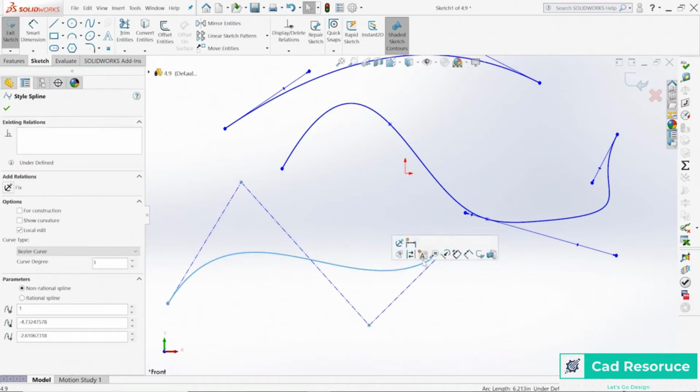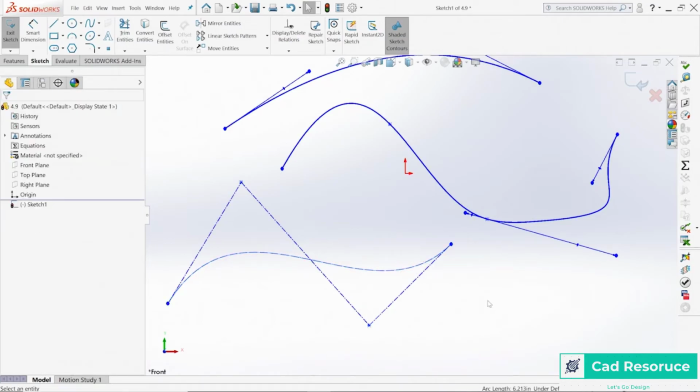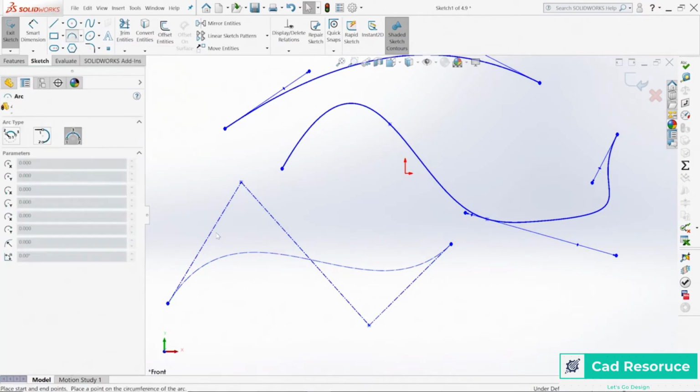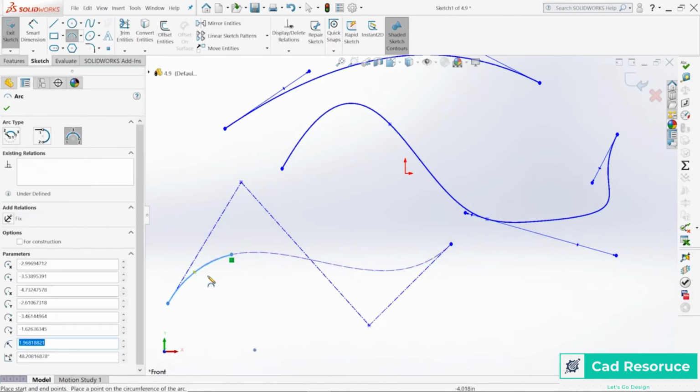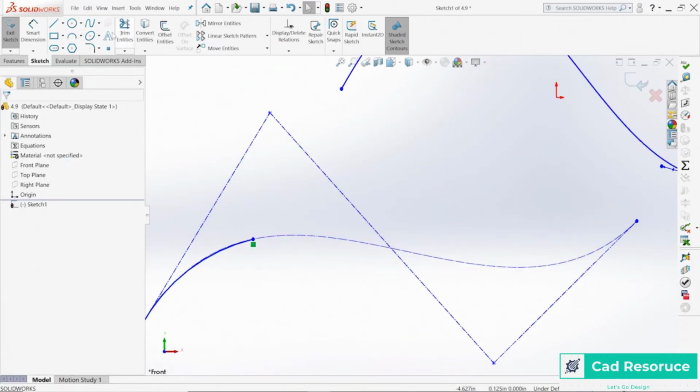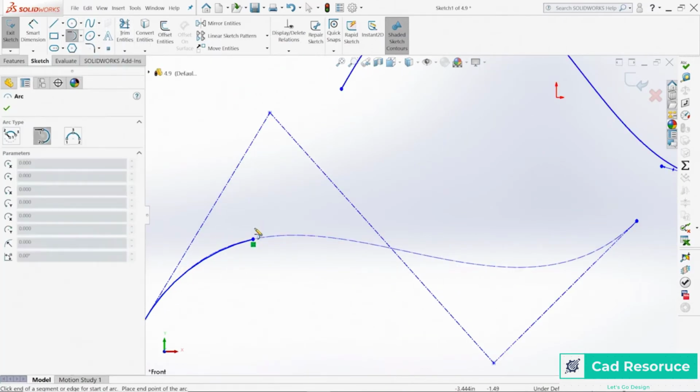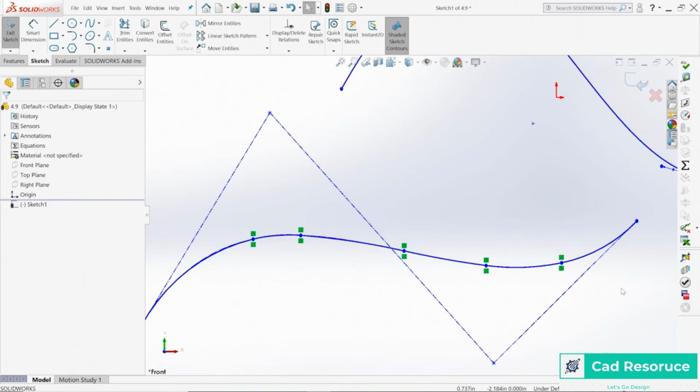In fact, another recommendation that you might want to consider is clicking on a spline itself and switching it over to construction geometry, and then doing what's called a best fit. So you can choose a 3-point curve and snap to that spline and get really close to that spline or that shape. And then maybe use a tangency arc, so you can follow that spline around and see if you can get a very similar shape to what it is.